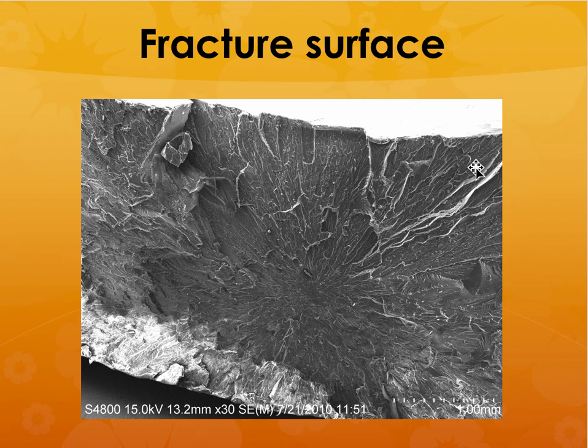If there is no necking, most of the time it is going to be a brittle material. In this case, you can see that the failure has started from one end or in the middle. Most of the time the place where the failure has started from is a defect which is beyond the critical size for the material, and so the failure starts from that point, releases that energy and fractures through the material in no time at all.